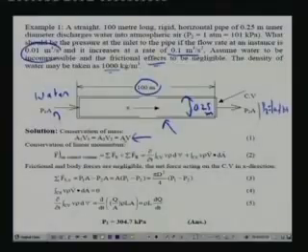That means whatever mass enters into the control volume must leave the control volume. Okay, so if you apply this, then you get the conservation of mass equation as A1 V1 is equal to A2 V2. And since the area is constant at every place, if it is a uniform cross section pipe, the velocity remains constant throughout the pipe. So this is basically the conservation of mass.